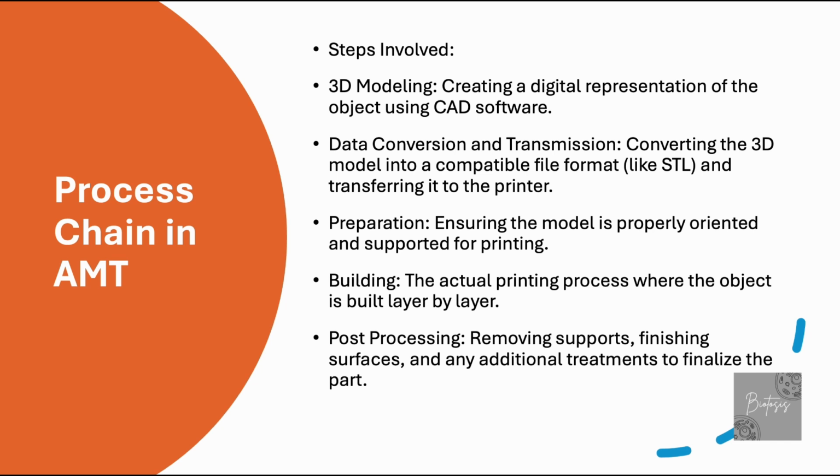As the printer is printing the material, the gel will get separated, like it will leave its place, and the structure that we want will stay intact, and in the rest of the parts the gel will be there to support it. The gel should not be so strong that the print head is not able to move properly. So all these things we have to keep in mind. What gel or what support bath are we talking about? As we move ahead in the subject, we'll understand it better.